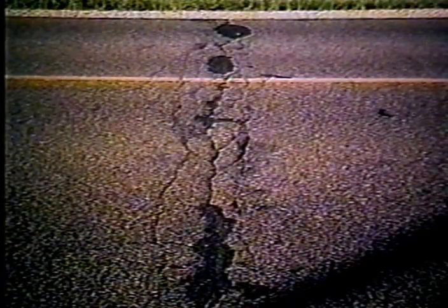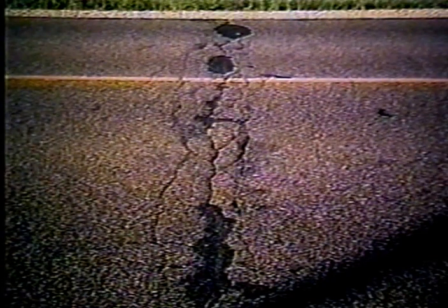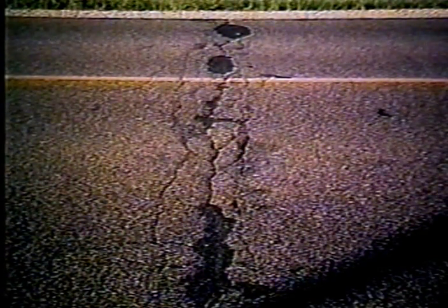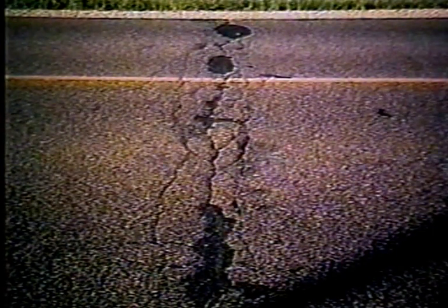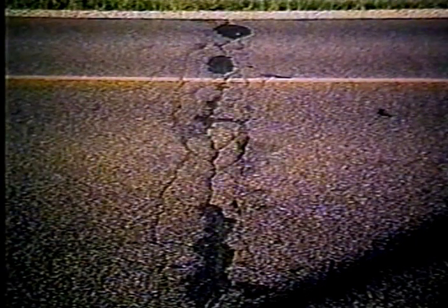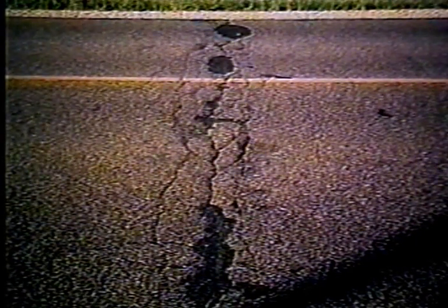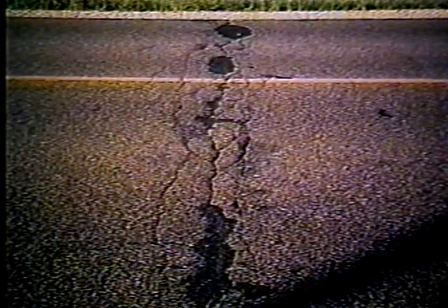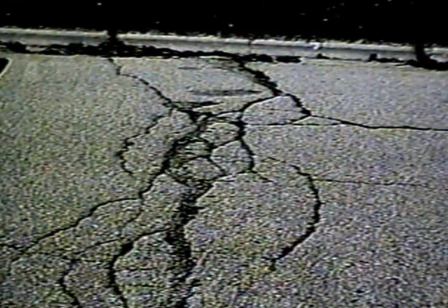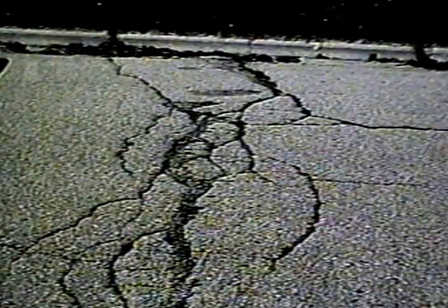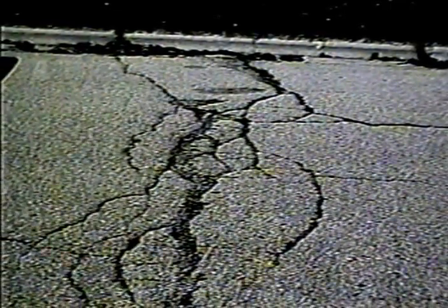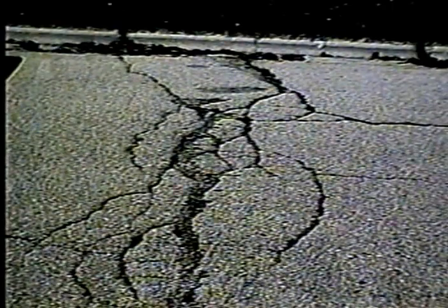More typically, what you see when you have an open crack, you see cracking develop on either side of the initial crack. Because you soften the base and soften the subgrade under the action of traffic, you get parallel cracks, and really you start to deteriorate the pavement. Another example of deterioration of what started out to be a hairline transverse crack, and because there was no attempt at crack sealing, you get additional deterioration.